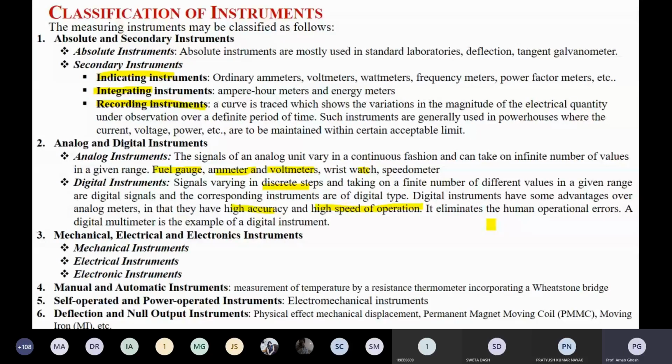You have to measure an unknown voltage, so you have to use a higher rated voltmeter. You don't know the actual voltage rating, so you have a 600 volt range voltmeter. You connect it directly to your circuit and measure the value. You see that your voltage is below 300 volts.